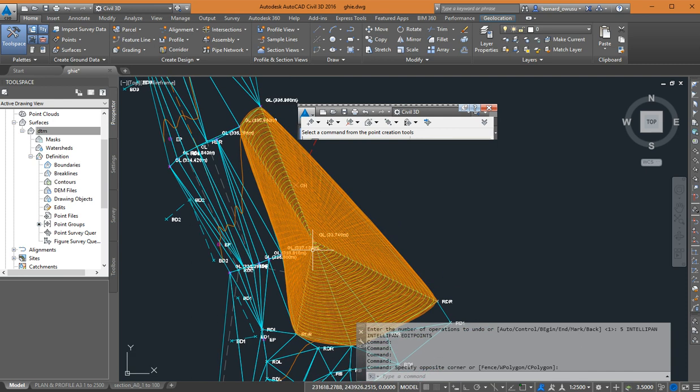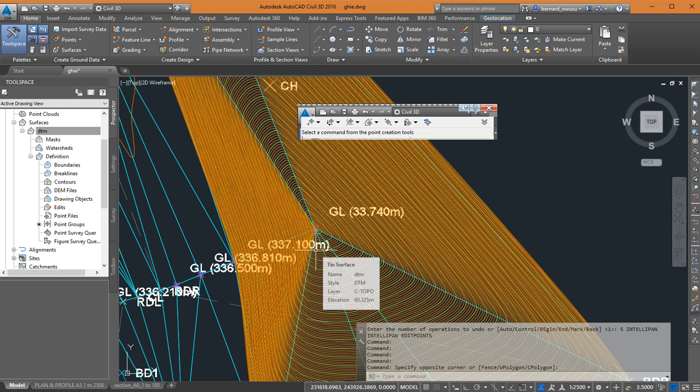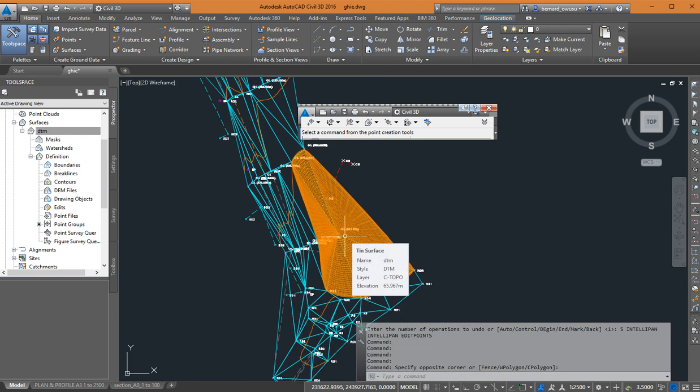And as we were taught, if contours are closely spaced, packed together, that means that it's steep. If they are wide apart, that means that it's almost flat. Now, once you see contours closely packed together like this, and you know that that place is not an escarpment, then it should tell you that there's a problem somewhere.